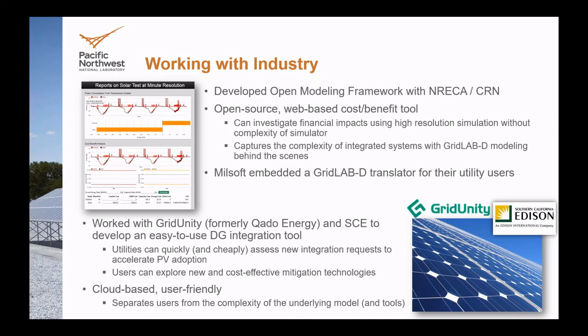You can go to the website. You can either use a sample distribution system they have already uploaded, or if your data is in the right format, you can upload it to their web server and do a lot of different evaluations of, if I deploy conservation voltage reduction, or if I want to do this type of upgrade to my system, what would the impacts be on that? And that web interface is actually running GridLAB-D under the hood to do a lot of the actual distribution system simulation and provide the results that it's analyzing and providing as feedback to the user via the web interface.